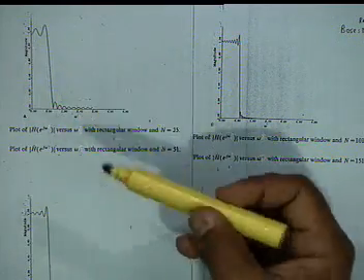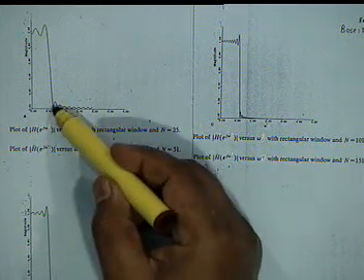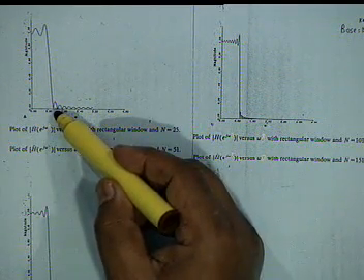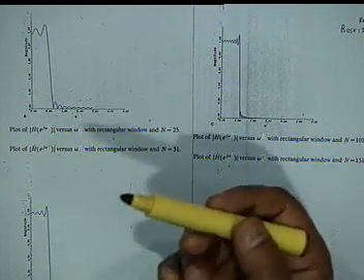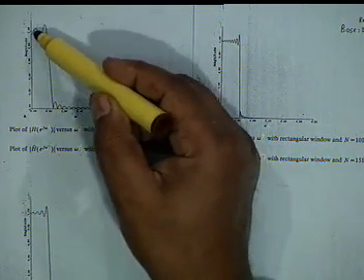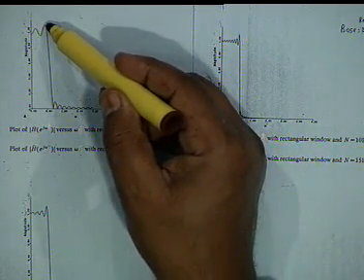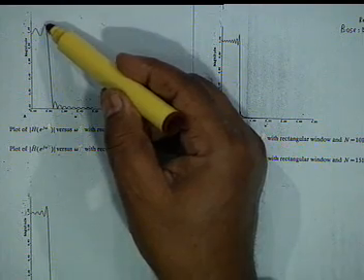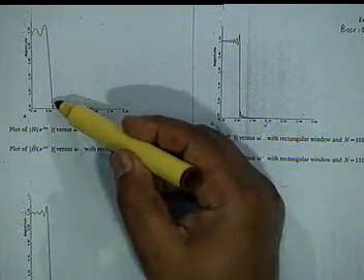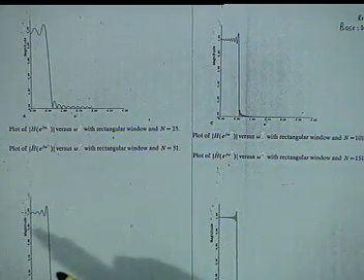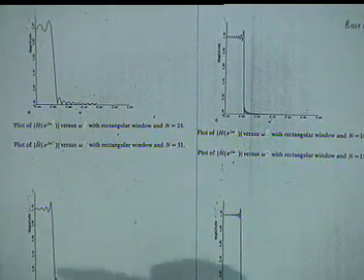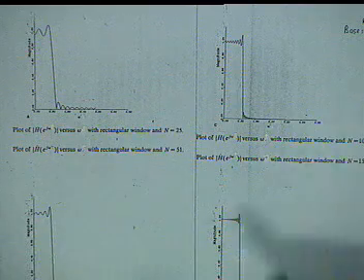We have plotted the magnitude, so we do not show undershoots. Okay? No undershoots, these are overshoots. Or the negative magnitude becomes positive. Okay? Now you notice that the value above unity, the last peak here and the first peak here, are almost of the same amplitude from the steady value, and this is 1.178.